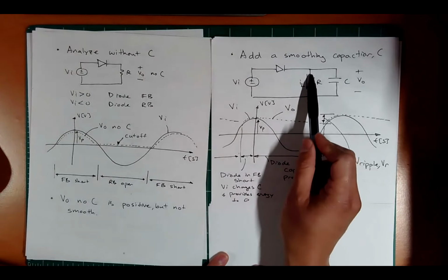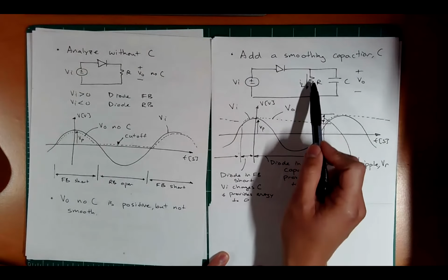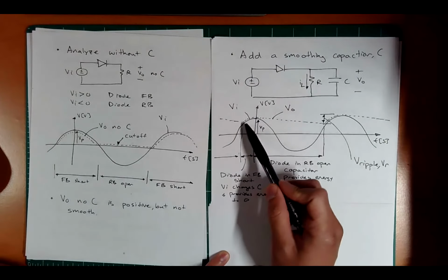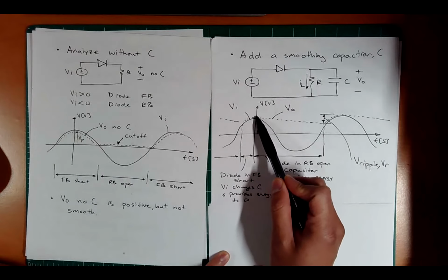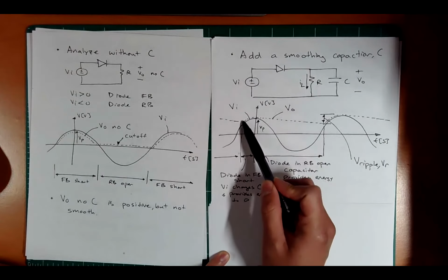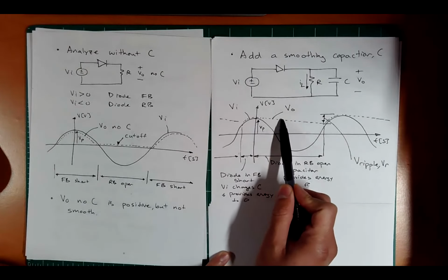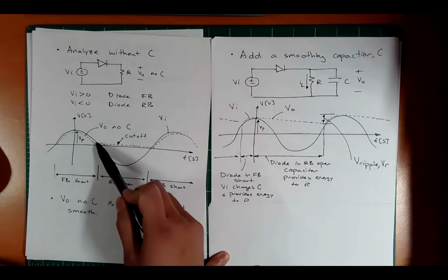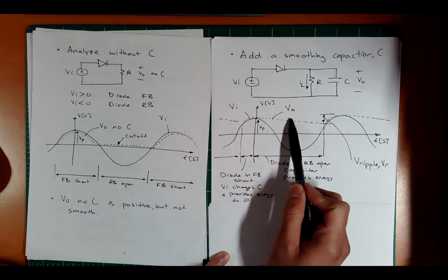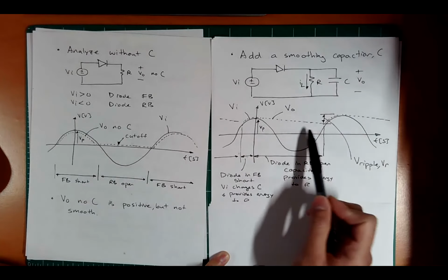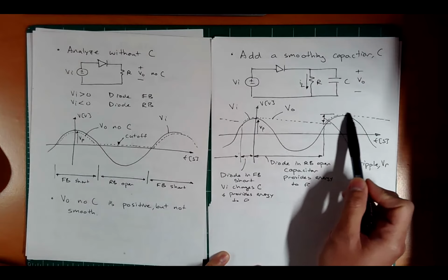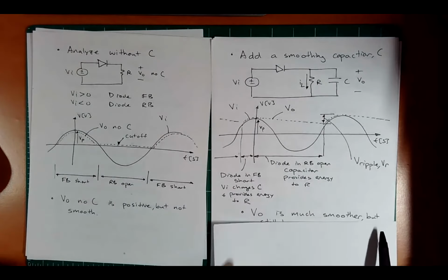You see this dashed line representing the output voltage here with the capacitor. So the input charges up the capacitor and provides current. And then once this diode shuts off, what happens? Now the V out actually doesn't drop down to zero anymore. It actually slowly decays at the time constant of this capacitor resistor setup, right? And then charges again, and the pattern repeats, right?